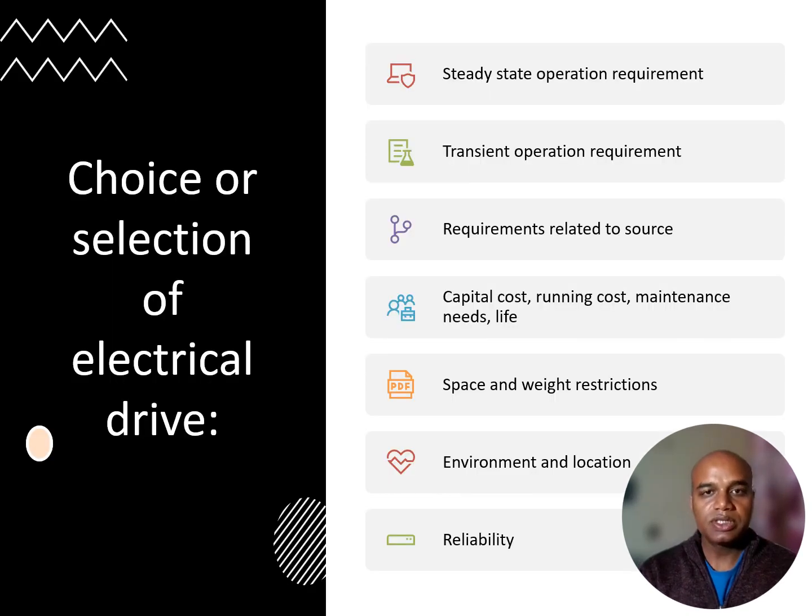So based on the requirements presented by the load, what are the factors that need to be considered to select an electrical drive or the electric motor? Number one is the steady state operation requirement. At steady state, how the load is going to behave, what is its torque requirement, what will be the speed.